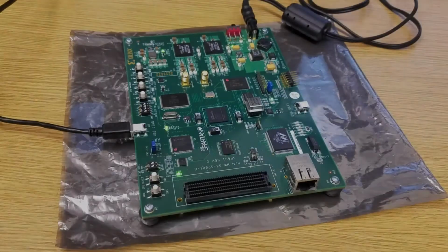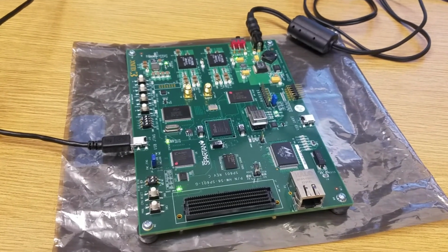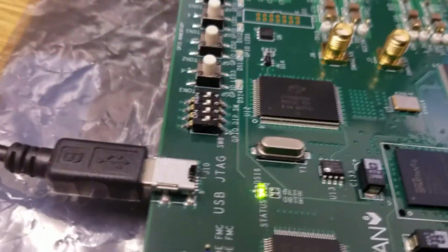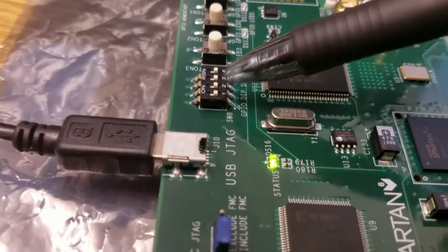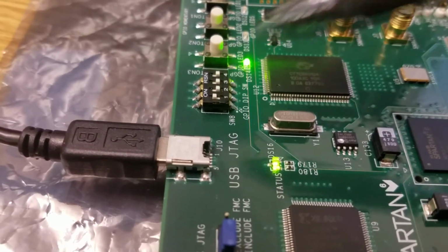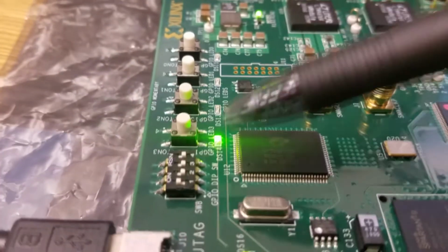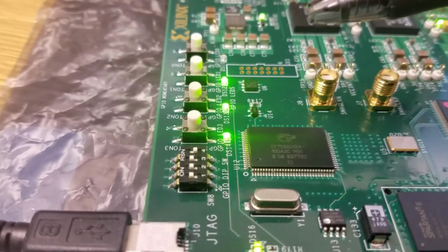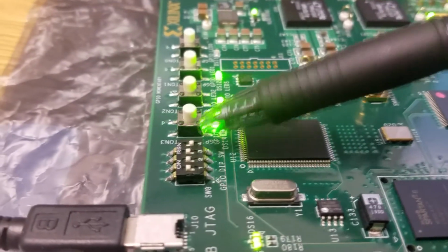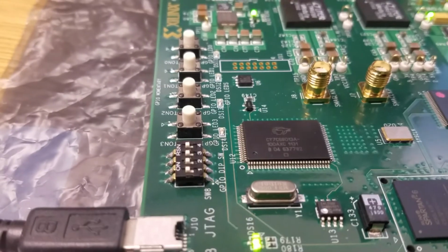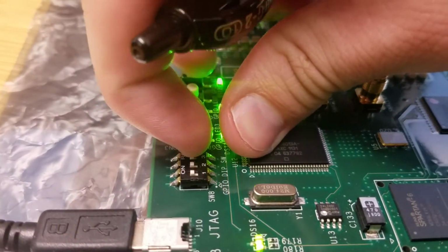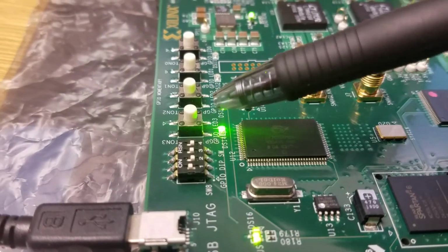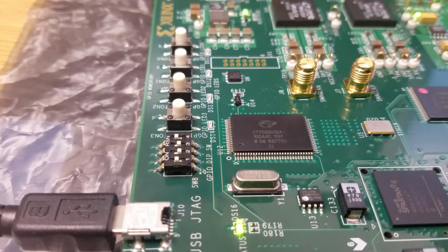Okay, so we just got the Spartan-6 to be programmed in the ISE software. So now the goal was to have these dip switches turn on these LEDs whenever you turn them on. So this first switch should turn on this first LED. There we go. Now the second switch should turn on the second, and third should turn on third. Now if you were to flip the last switch on, which we have as reset, this should turn off all the LEDs. And there we go. So let's turn that off. LEDs come back on. Like I said, it doesn't matter what state the LEDs are in, so we turn that back on. And there we go.